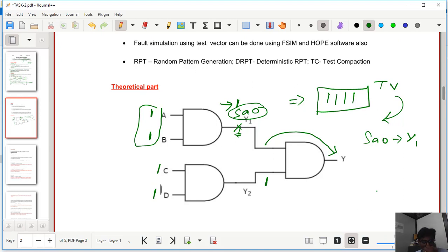Here we have a simple 3 gate circuit and we try to figure out, assuming that here and there some fault is present. In order to capture that fault, we are trying to generate the corresponding test vector which will capture that fault. The same thing needs to be done with thousands of gates, and we are supposed to generate the appropriate test vector for it.